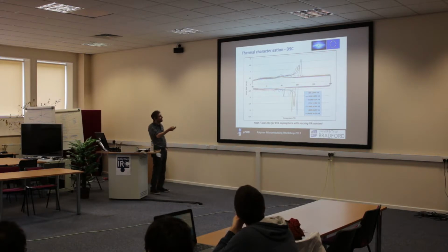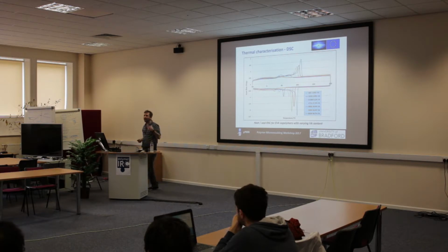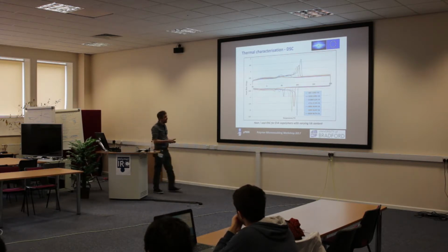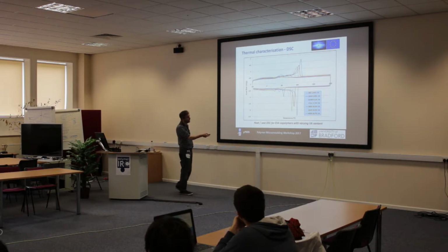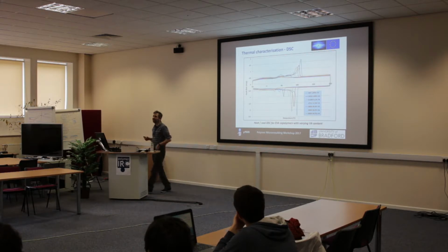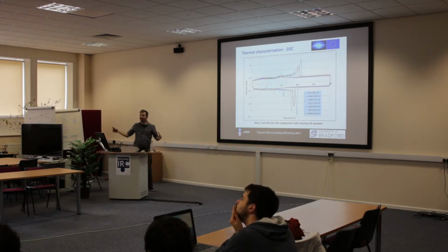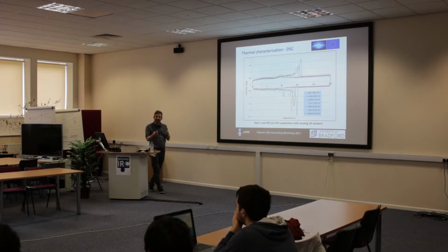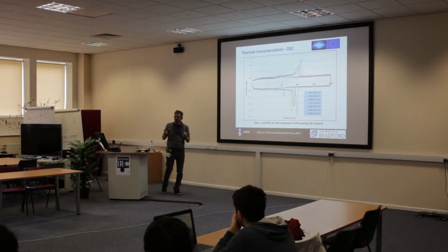All right, these are these vinyl acetate copolymers. Basically they're polyethylene with a vinyl acetate comonomer in them, polymerized together at different percentages. This one, the low one at 2% VA, is used for greenhouses and for growing plants, etc. It's the plastic sheeting. It's got a bit of stretch to it, but not very much.